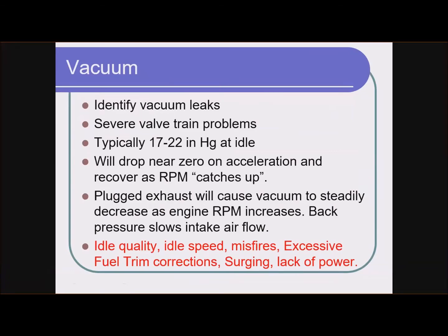But another way, I'll show you that picture in a minute, is something that I ran into 40 years ago, 35 years ago, that was actually diagnosed as a bad engine, and it was a vacuum leak. Another thing that might make you do a vacuum test: excessive fuel trim corrections, right? Surging, we talked about that with the fuel pressure, or lack of power.